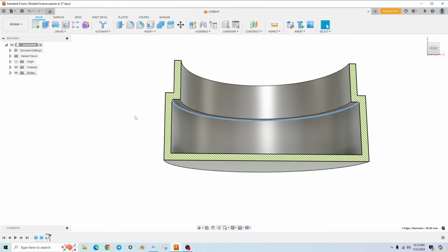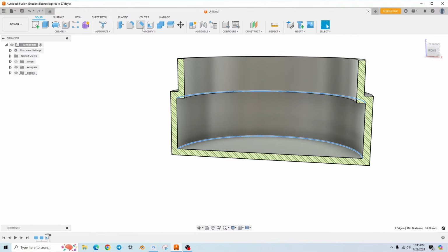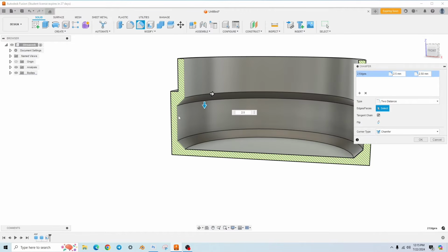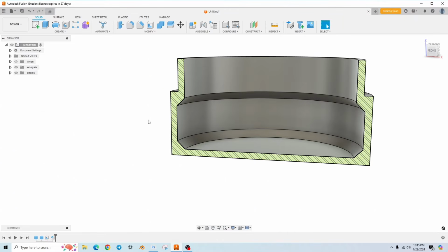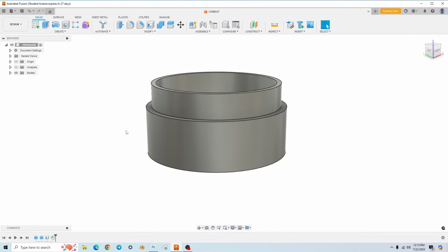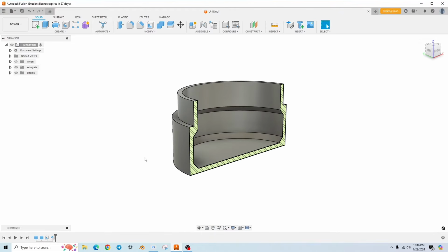I'm going to do a quick chamfer here because we are going to 3D print this. I know from experience this is 2.5, and actually might be like 2.4. Let's keep going down, 2.3. Yeah, let's just keep it at 2.5. It doesn't matter. And that just strengthens this bottom connection when you 3D print, and then gets rid of this overhang here. So this will 3D print nicely. So if I turn the analysis off, there's my real small jar.